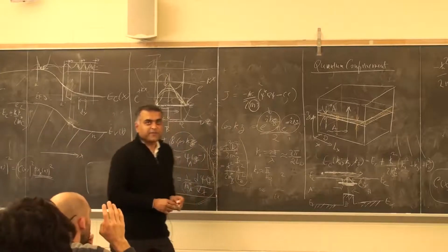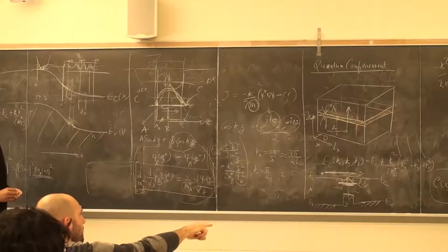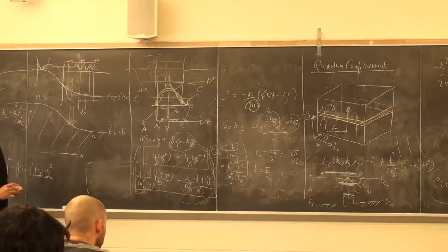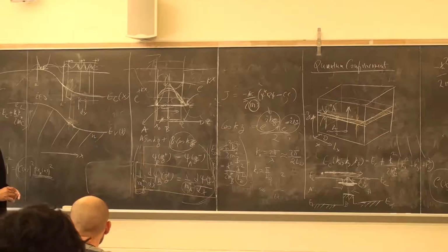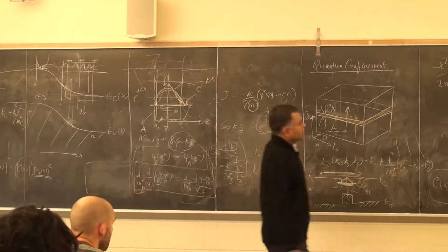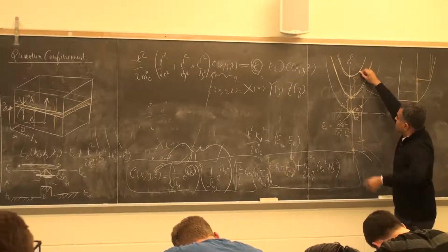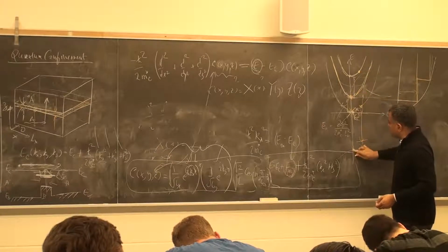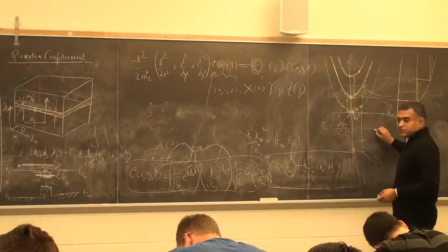Yeah. You said we could tune the wavelength of the light emitted, and that's true if it's jumping from the valence band to the conduction band, but now we have these bands that are modified by the quantum well. Mm-hmm. But now doesn't it also have the possibility to jump between the first subband and the second subband? Very good point, yeah. And I will come to that at some point in this class. So what John, you are asking is, clearly I can put an electron here and empty out this state, which is a hole, and then I can recombine here to emit a photon.